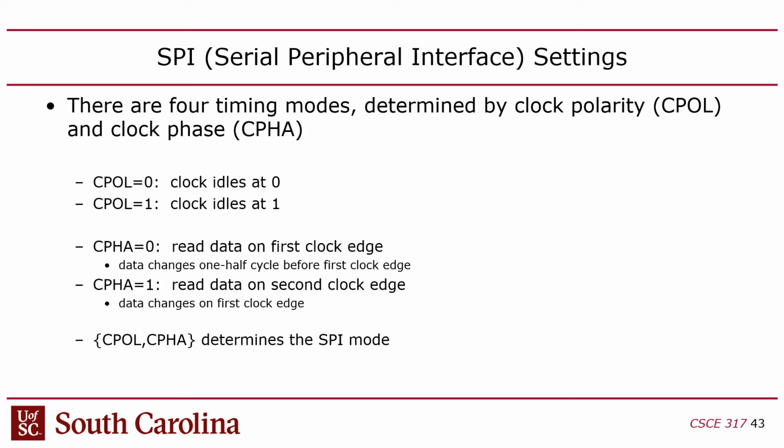The other option is CPHA, which stands for clock phase. Now this one is the one that's a little bit more confusing. So CPHA defines, think of it from the slave's point of view. Okay, so the slave is seeing data come in. When data is read, it's latched, it's sampled in a flip-flop.